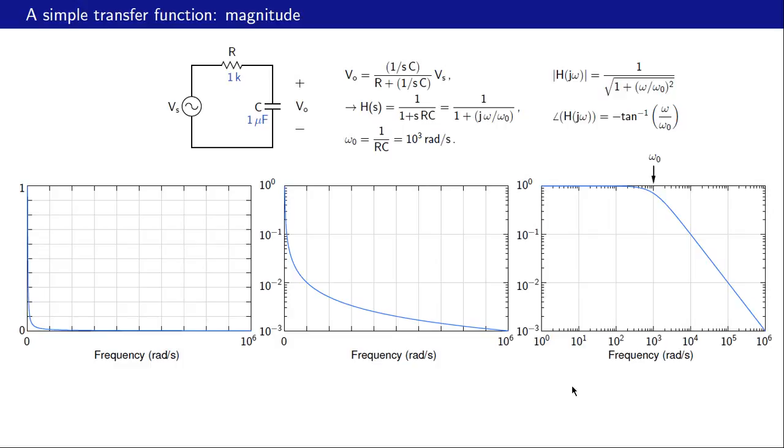What can be done is to replace the linear x-axis with a logarithmic x-axis as shown in this figure. This is omega equal to 10 raised to 0, 10 raised to 1, 10 raised to 2 and so on. And now we can very clearly, easily distinguish between different frequencies. And now it is easy to read the mod of h value for a given frequency. For example, at 10 raised to 2, it is 1, at 10 raised to 3, it is something like maybe 7 times 10 raised to minus 1, etc.